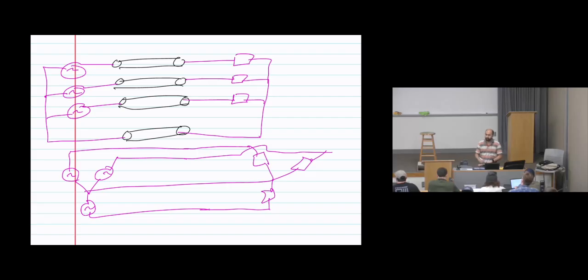So the top and the bottom are exactly the same, but I make the shape so it looks like a Y. So this is called Y, or sometimes star. It looks like a star or a Y connection. Some textbooks call it Y, some call it star. So this is the connection for the source. And how many conductors do we have? 1, 2, 3, 4. So star connection or Y connection can be used for a balanced situation.